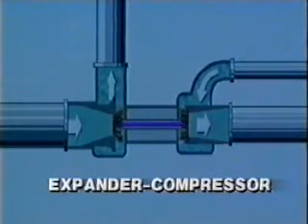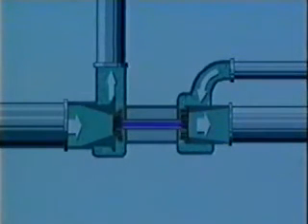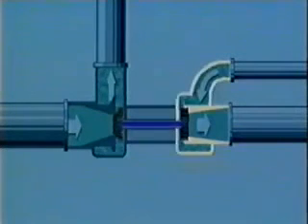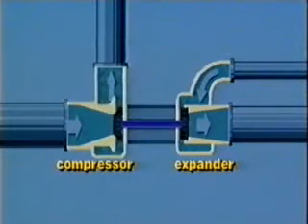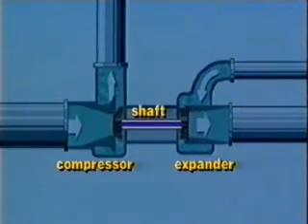In expansion, the gas stream passes through an expander compressor. An expander compressor is a device which has two separate units, the expander and the compressor. These units are separate, but share a common shaft which transfers energy from the inlet gas in the expander to the compressor, where the gas stream returns to the expander compressor downstream in the process.